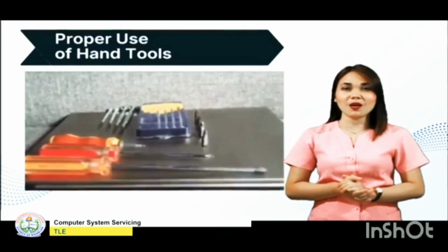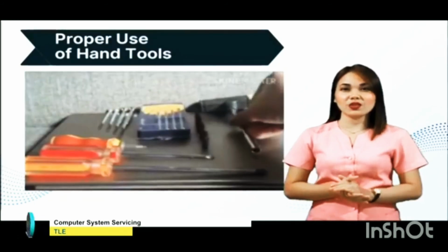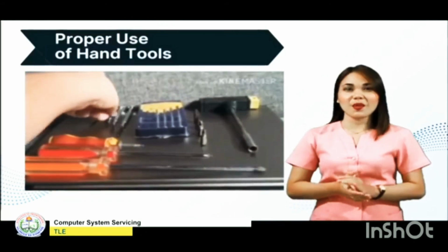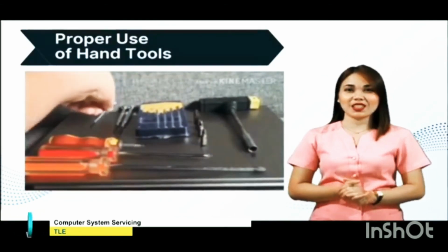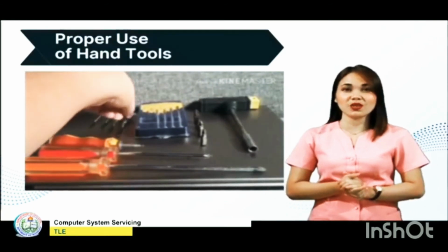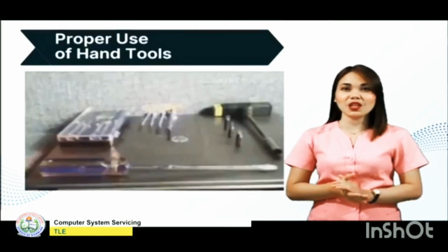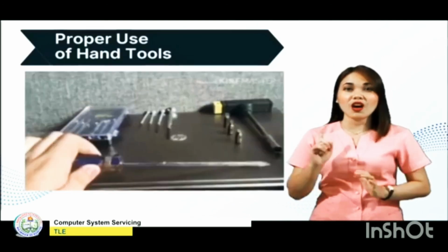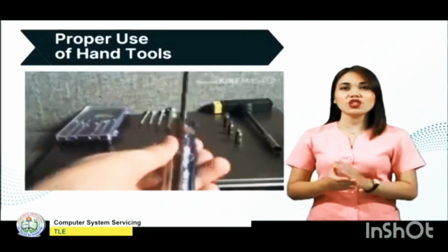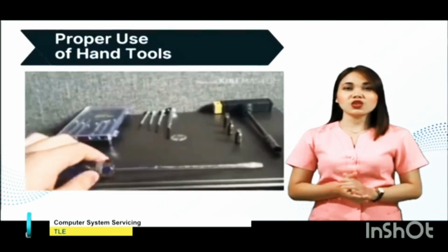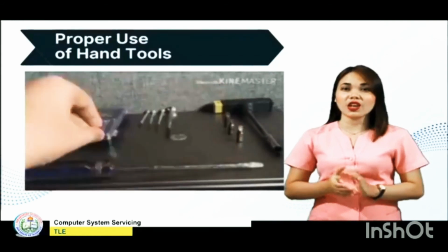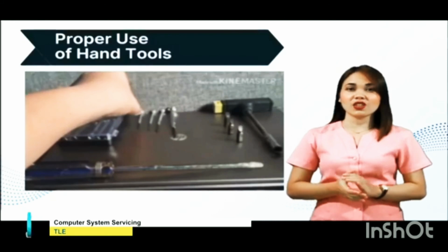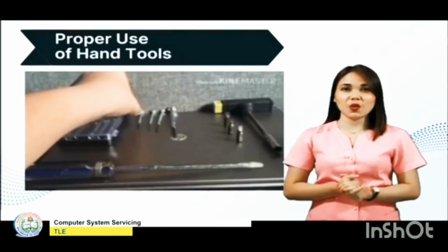Some tools are magnetized. When working around electronic devices, be sure that the tools you are using are not magnetized. Magnetic fields can be harmful to data stored on magnetic media. Test your tool by touching the tool with a screw. If the screw is attracted to the tool, do not use it. Pencils should not be used inside a computer to change the setting of switches or to pry off jumpers. The pencil lead can act as a conductor and may damage the computer components.